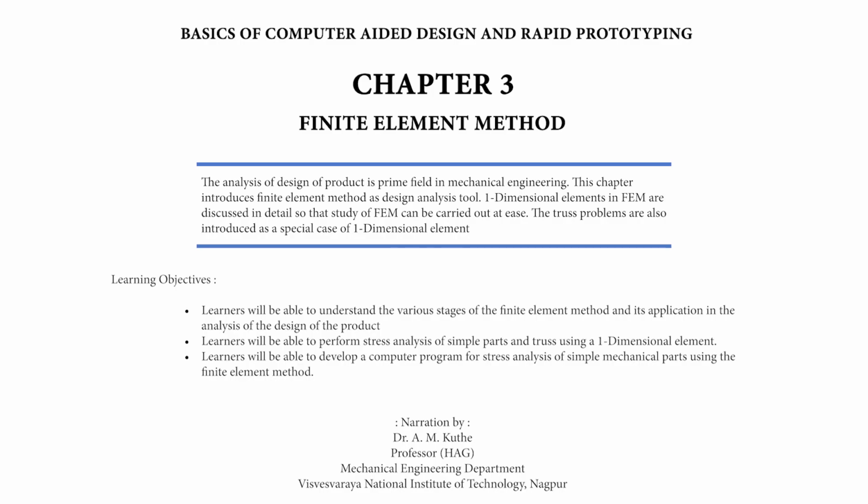Para 3.1.1 Discretization. This is the first and the most important stage of the finite element method. The complete body, hence onward called continuum, is divided into elements and nodes. The connectivity of elements is through nodes. In figure 3.2, the cantilever is discretized into 12 elements and 21 nodes. The value of the field variable, that is displacement, is found out at nodal points.